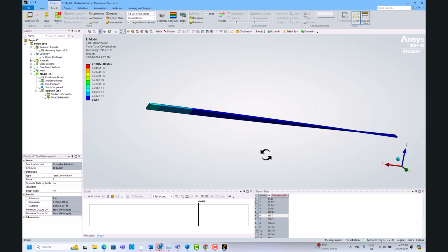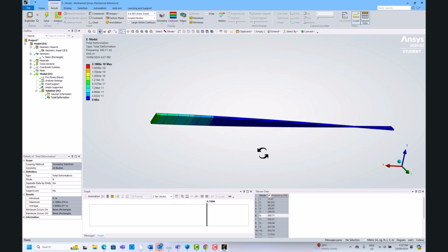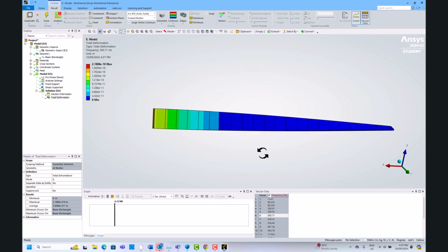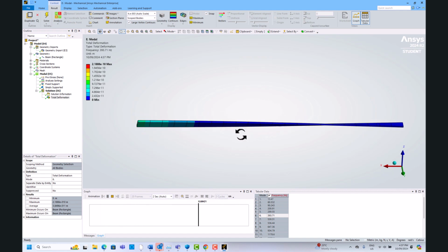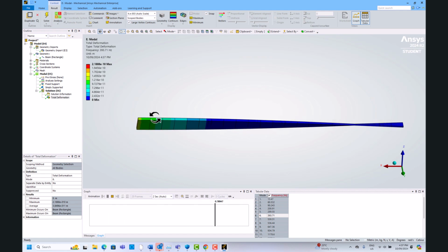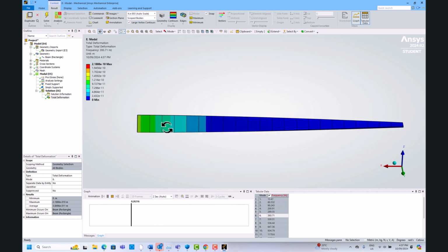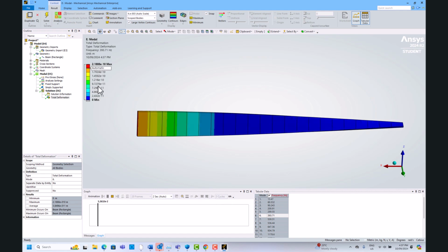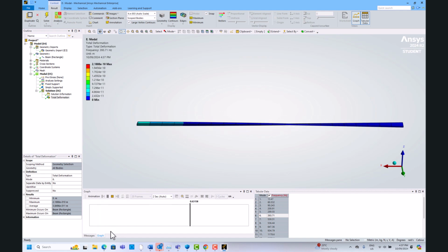Okay? So that's also in your assignment. So you have to find the torsional mode. You have to look into your solution to identify which one is your torsional mode. And obviously you need to plot the mode shapes like this. You see this mode shape doesn't look right. We have a lot of area being blue. The shape looks right, but the contour, the color doesn't look right. And also you see those numbers are extremely small, right? So I made a note here.